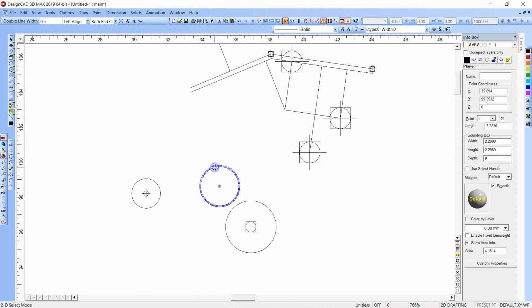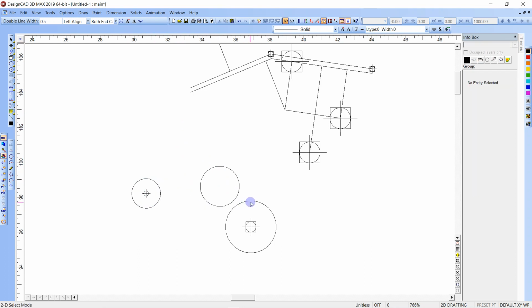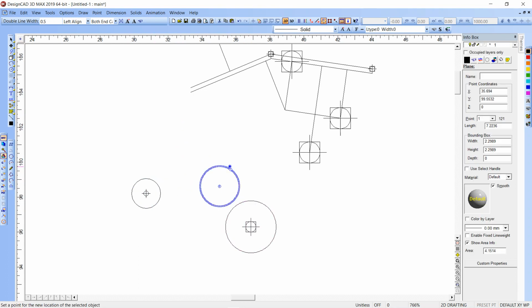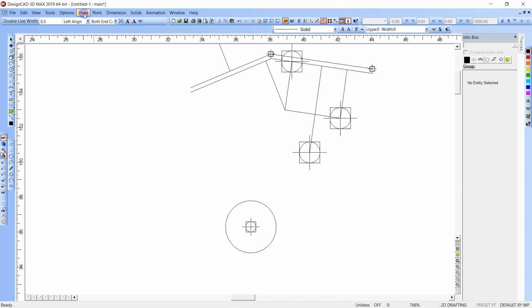And then here we go. So is this a circle? No. That's not a circle. That's a circle. Delete. Delete. So draw, same thing, right? From anywhere on the drawing, it'll draw a tangent line to that circle. F3 from here to that side. All you gotta do is tell it which side. And then if you had another circle, O, circle,